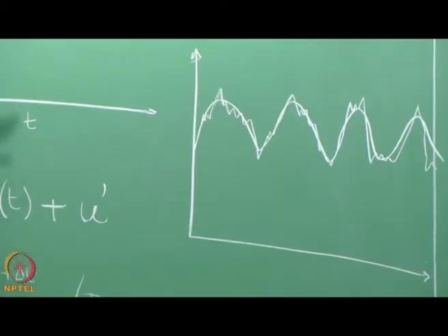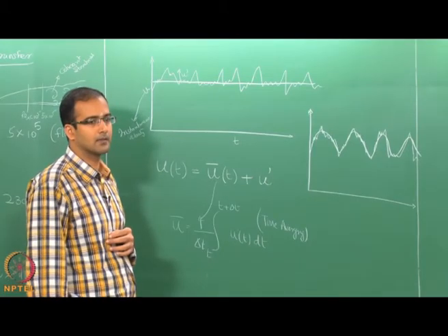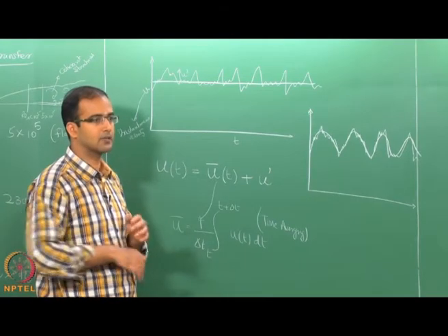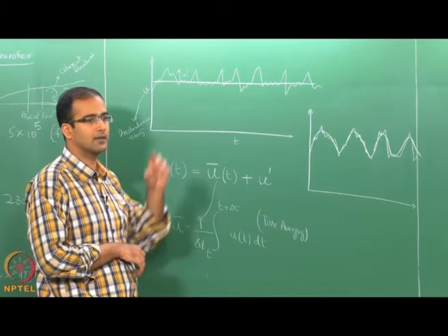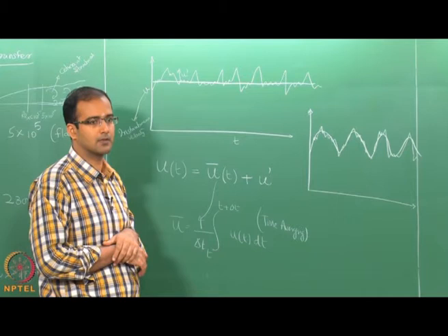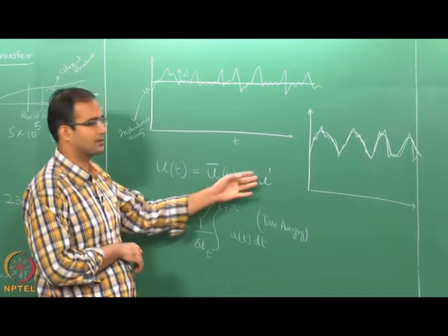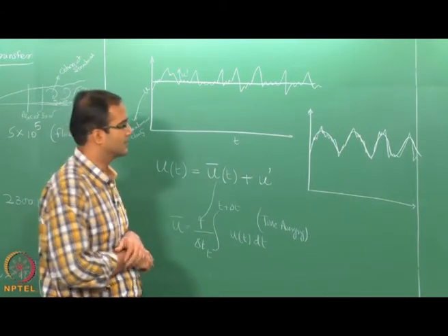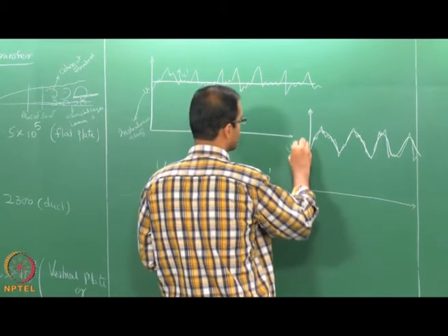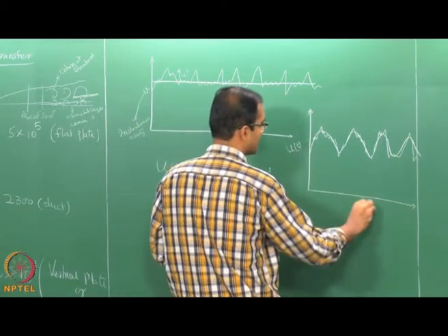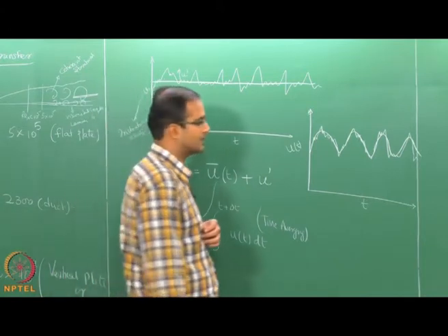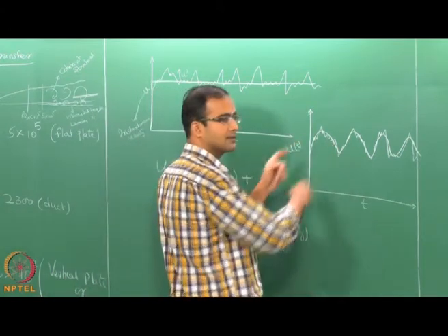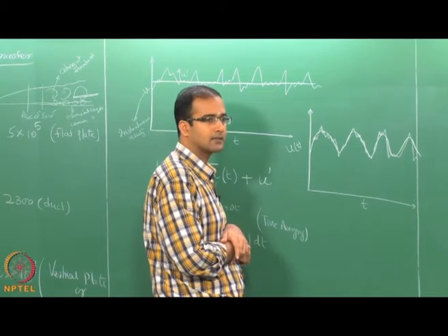Understand? So, these are not small fluctuations. You should distinguish the waviness, which is actually the time variation of the mean velocity, from the fluctuation, which is your RMS velocity or root mean square velocity. So, if you plot the instantaneous velocity here and carefully apply the time filter, such that this time filter is smaller than the waviness.